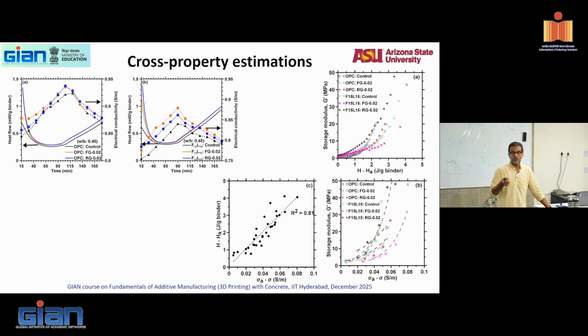But that'll be an interesting work to do, because once you track rheology, which you can, once you track hydration, which you can, there is no reason why extrudability and buildability cannot be inferred from conductivity measurements. Maybe not simple conductivity, but maybe some impedance kind of measurements. That's my feeling. I haven't really done it, but I will have to do it at some point of time when my students are happy enough to do more work.